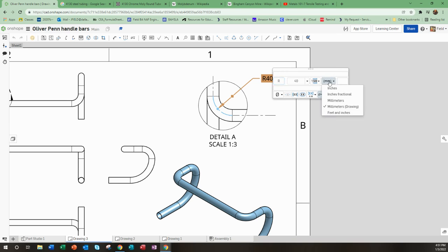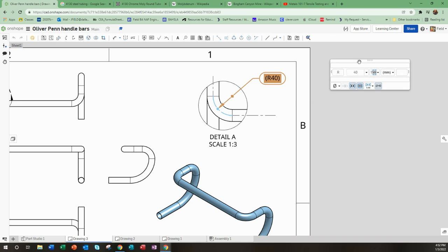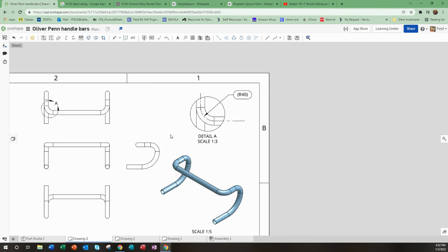of a tolerance. You can change your units or whatnot here, and you can put more information here in this blank cell, and then there's other information. You can make it a reference dimension, or you can make it a dimension that must be measured every time you make the part. That's what this would indicate. This would mean reference, meaning it's not a driven dimension. It's just there for the viewer to see what it is. I can toggle between diameter, that's that symbol, and radius, okay? So a lot of stuff you can do when you dimension stuff like that.